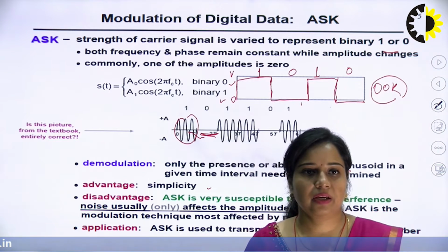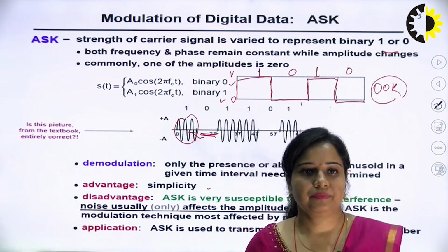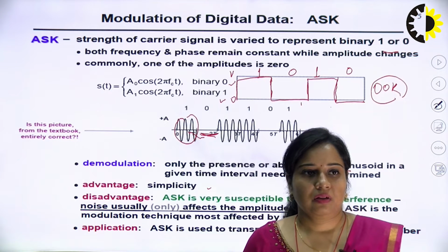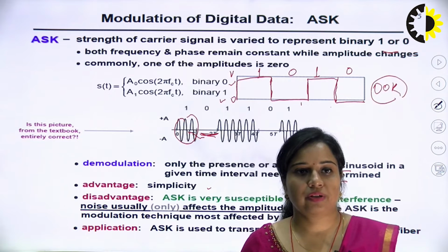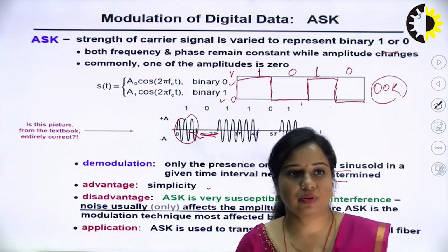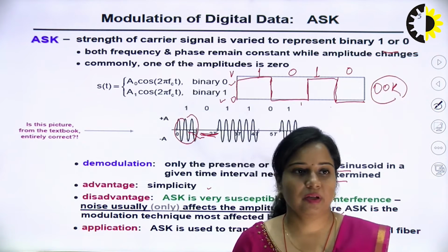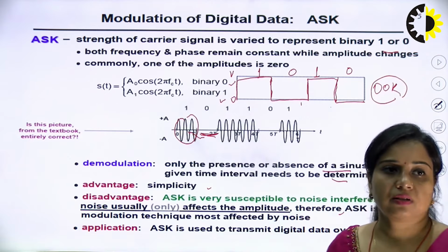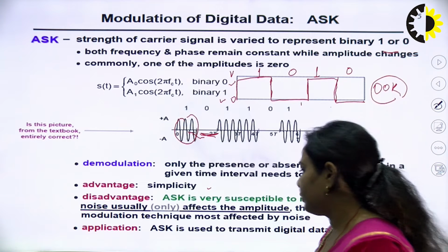So, that is why we have to consider that noise will mostly affect the amplitude of the signal, and we are changing only that, we are considering only that information. So, definitely there will be noise which you have to consider in ASK.